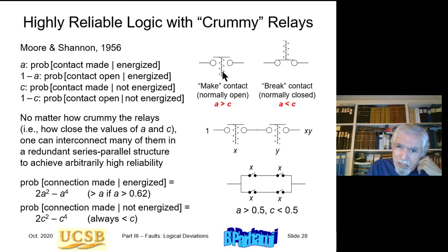So this magnetizes basically this area, and then it pulls the relay down and closes it. And this is a normally closed relay that can be opened by asserting this signal. Of course, a normally open relay should be open. If it closes, then that's considered a fault. A normally closed relay should be closed, and if it opens without the assertion of the signal, then that's a fault. Similarly here, if this closes without the assertion of the signal, that's a fault.